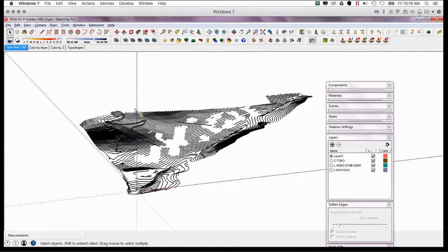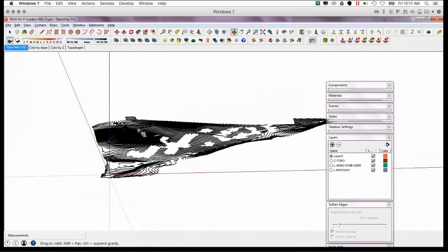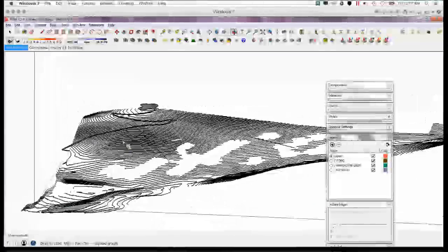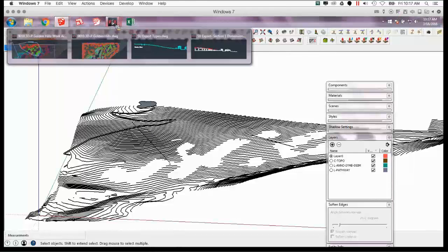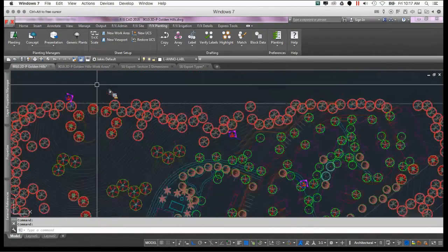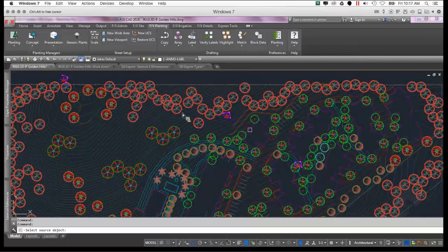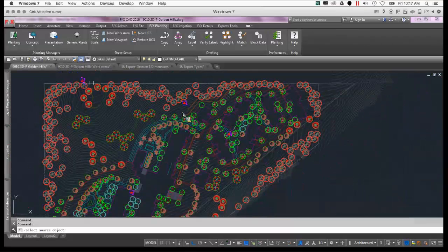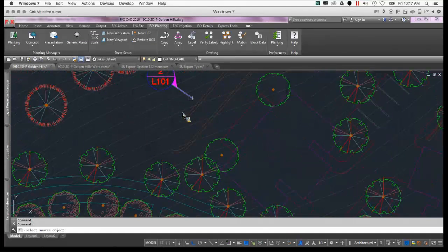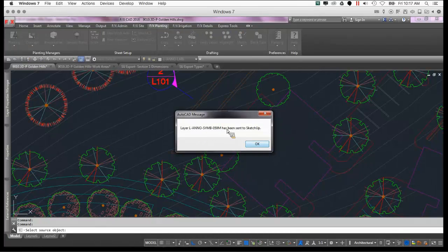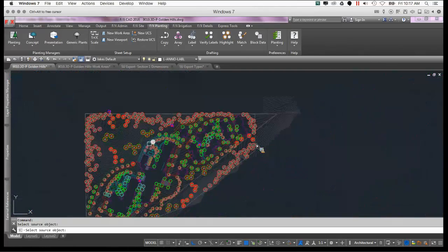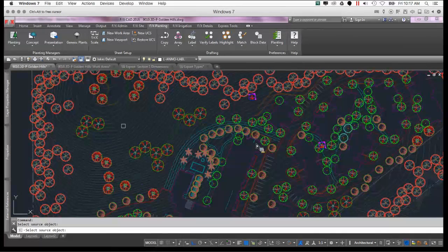All right, so I want to quickly go over a couple different plugins that we've found that may or may not work for your workflow, but they're an interesting idea. So see how you can use these things. Essentially, we are using the SketchUp Connection, just like we were doing over here in AutoCAD. And what I did here is I sent the layers using our SketchUp Connection, and I predetermined where I want these section cuts to go. This is where I think I want them to match up for my different views. And so I sent this layer, the anno symbol layer, for that section cut callout, and sent him over to SketchUp along with my topography and any relative line work that I need for making that model.